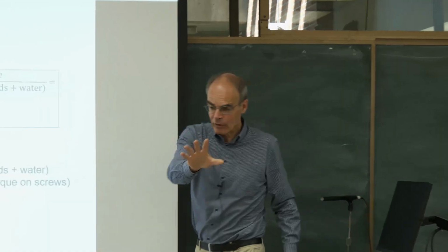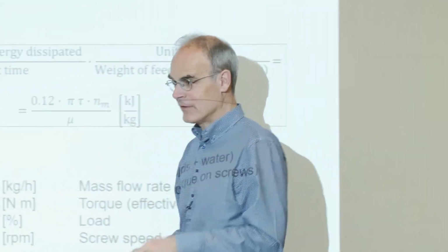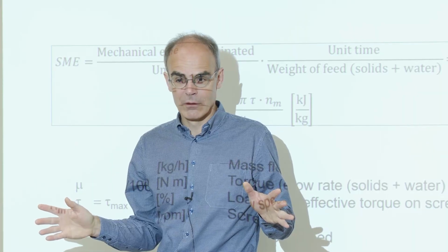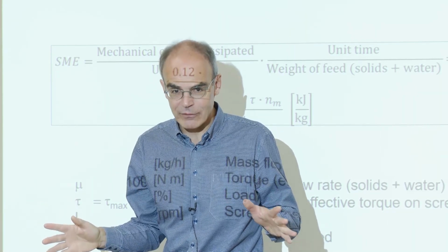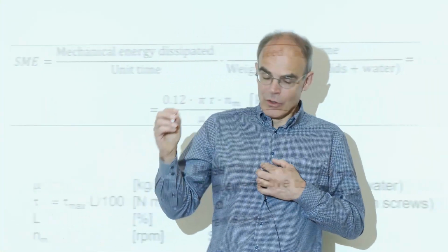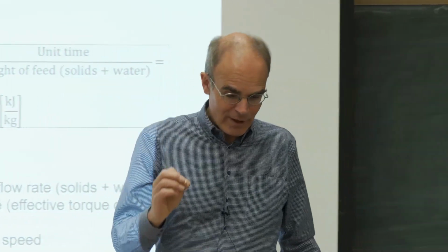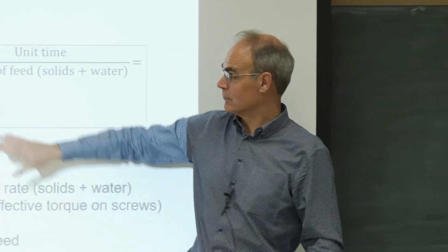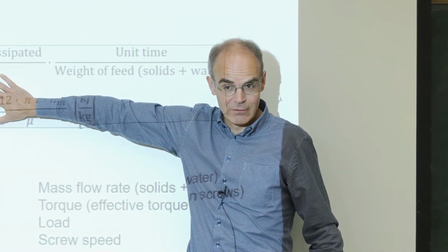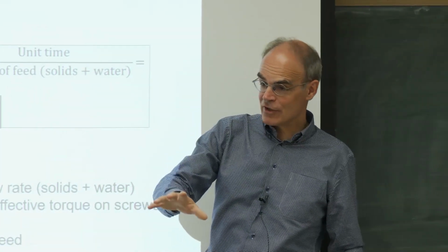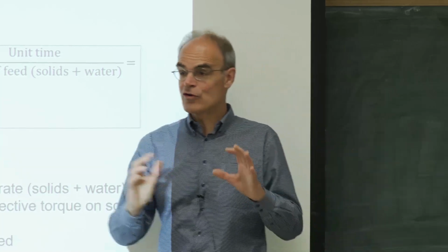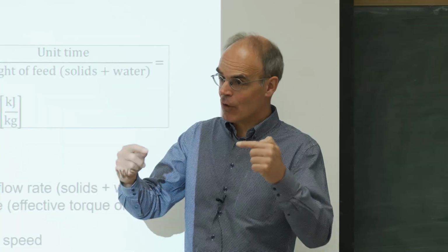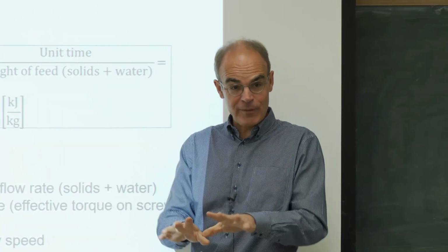Yeah? There's one other aspect. So I'm dissipating that energy. Where is it going? What is happening with the temperature? Increases. So typically, as I mentioned yesterday, an extruder is very good at shearing, over that SME. An extruder is really poor for heat transfer, especially big extruders. You almost don't lose heat. So during that shearing, especially when I have a high viscosity material, typically low water content.